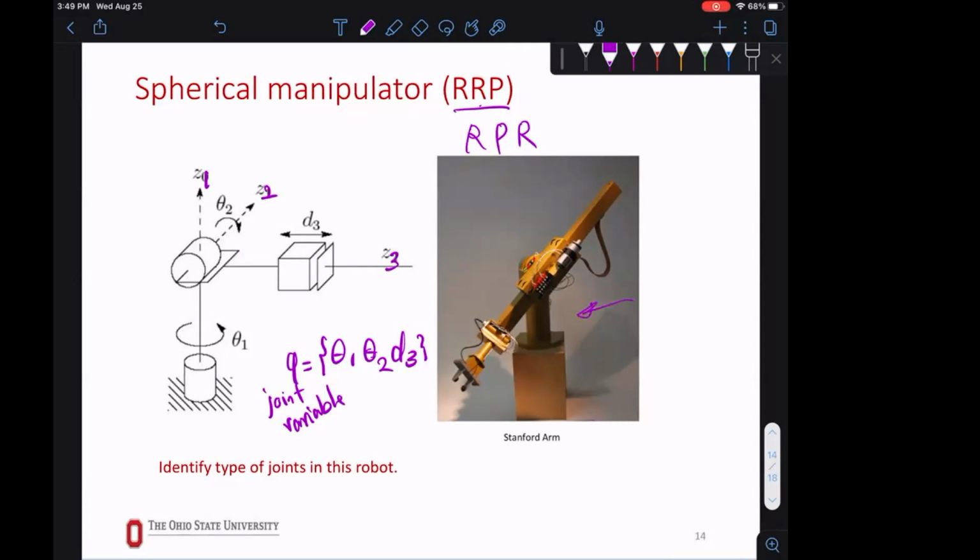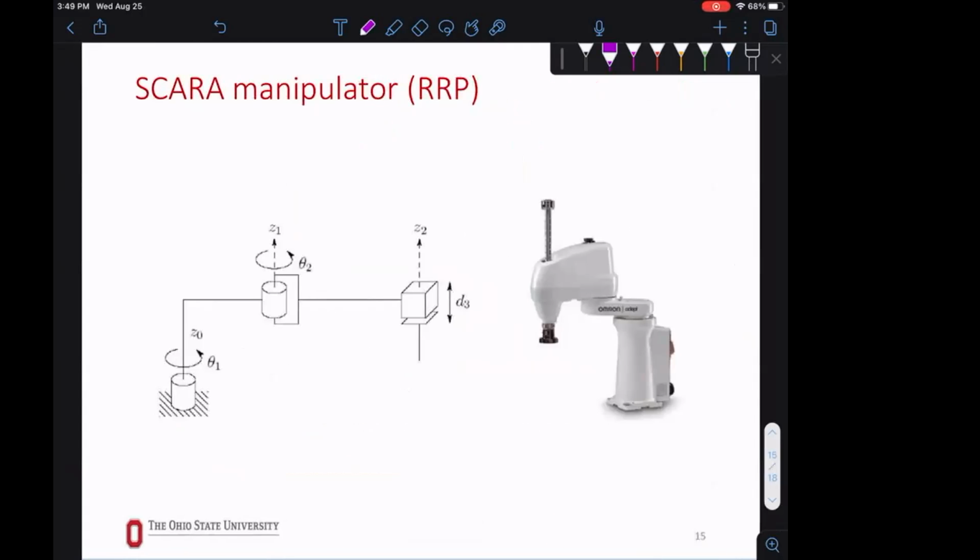This robot is good for shooting down, pointing lasers. It rotates, moves, and can have an effect to do anything. So these two are kind of shoulder. But if you are this robot, it's a different capability. The direction of the z-axes are different. They're both pointed upward, Z1, Z2. This I'm going to call Z3 because I'm trying to match for now with this one.